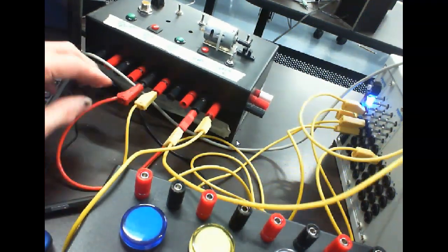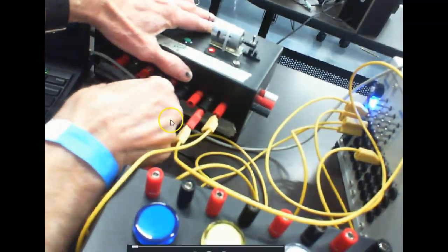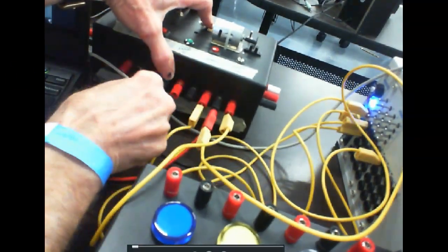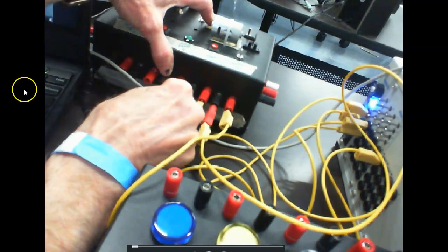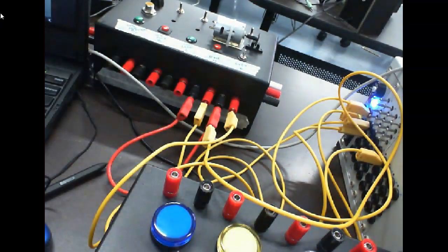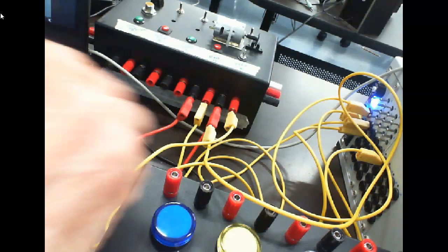So this is my normally closed. I could move it over to this normally open. So what I would do if I was going to use all these inputs is I would take the plus and jump it to all of them. And we just have red and black. You could use the reds as common, and these are nothing but push buttons, and use the black as the actual switch.